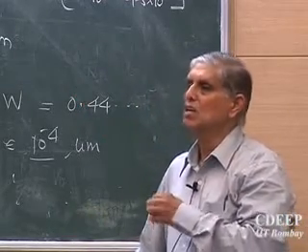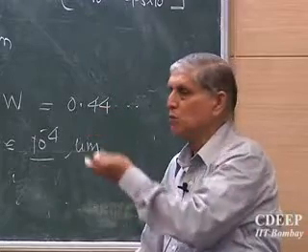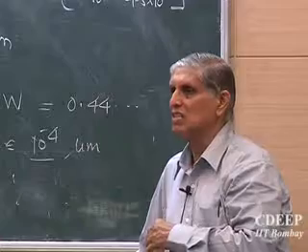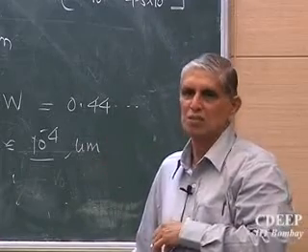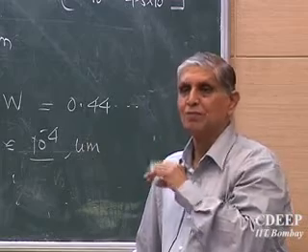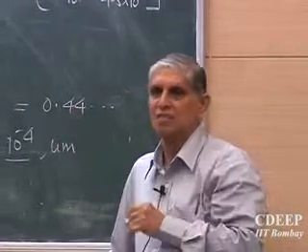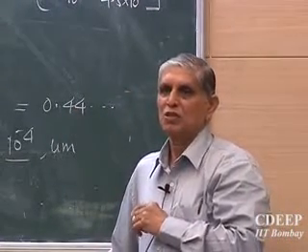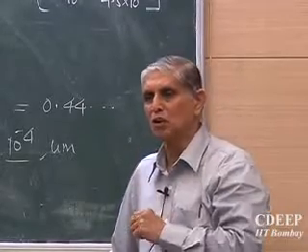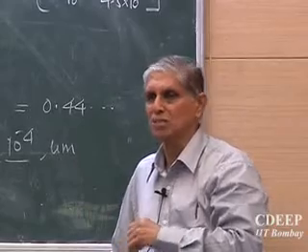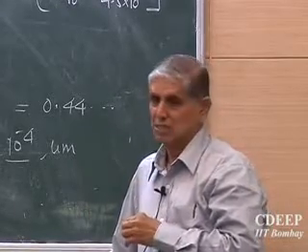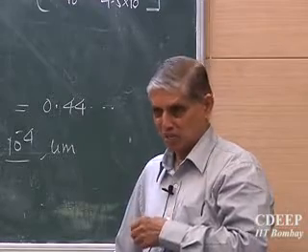Is that okay? So xpo is normally very small if a P plus N junction is used. Contrary to this, if you have an N plus P junction, the opposite may occur: all the depletion may go on the P side, nothing much on the N side. Is that clear? But if they are equal, then it will be half on both sides. So depending on the dopings used, I can know which side the depletion goes on, or how much on the left and how much on the right of the junction, which I can always evaluate, provided I am given NA and ND and the temperature at which I am working.